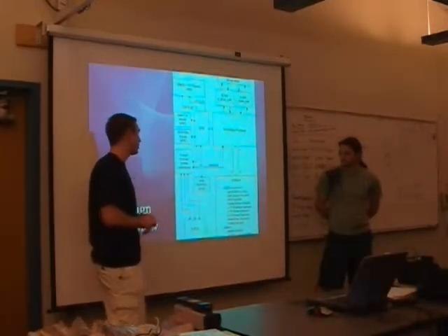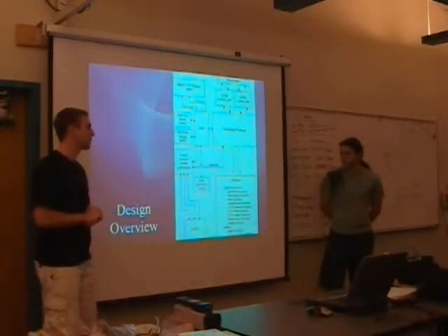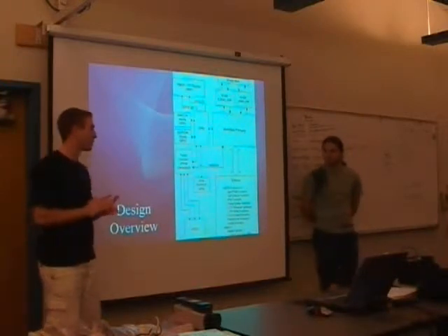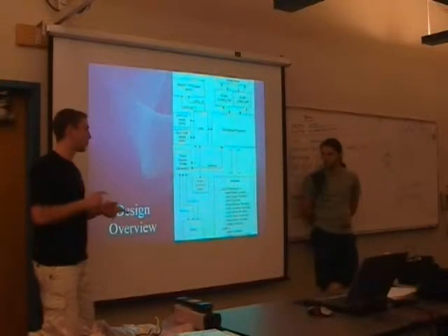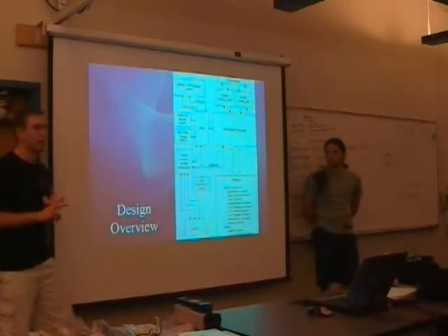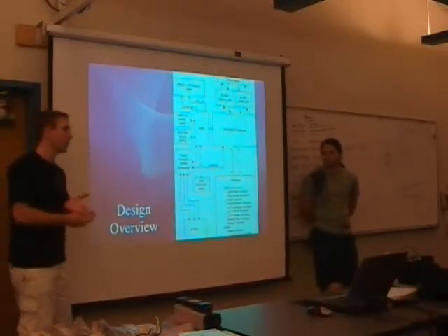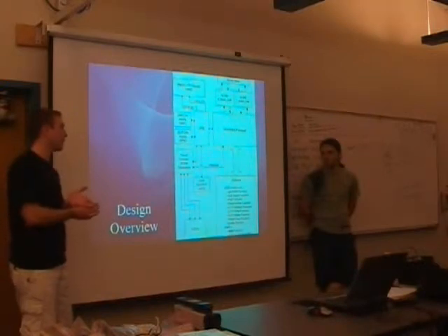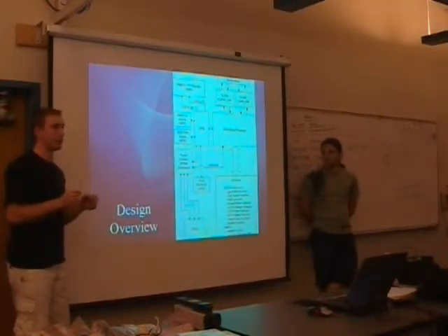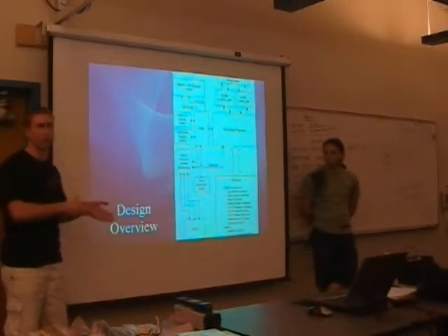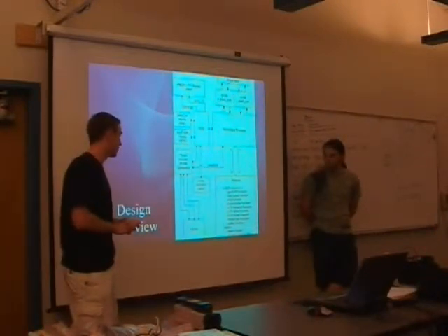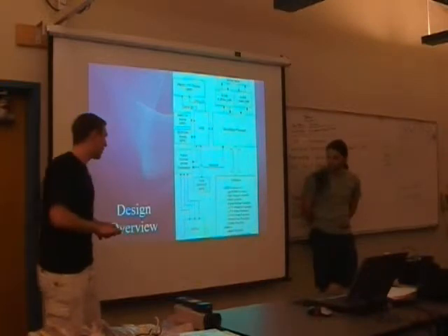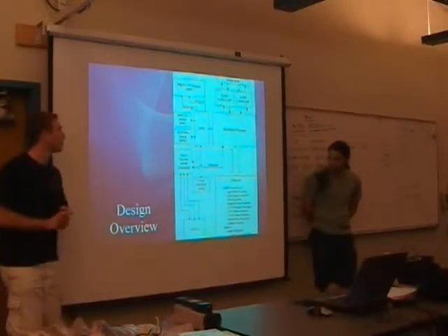The main function was gen PWM, which generates the specified PWM signal that we want for the specified colors. Then there's the set-out function I talked about, and the poll function just polls all of the switches and buttons. It does debouncing. It also acts like an asynchronous interrupt, so that tells it when it needs to stop doing that certain preset and go on to something else. And all the LCD functions are the same as all the previous labs, and that's basically it for the software functions.